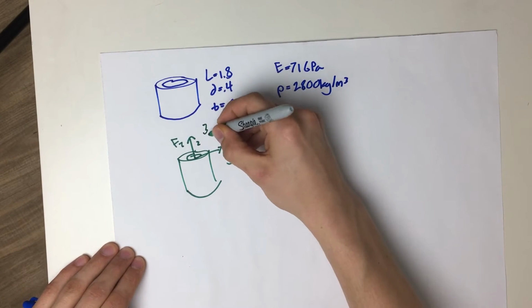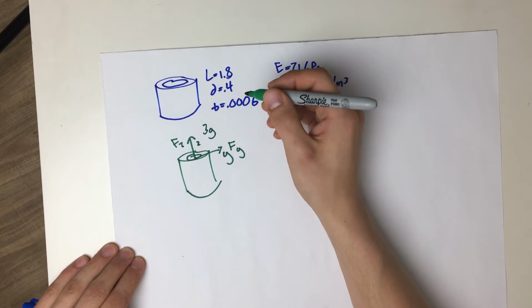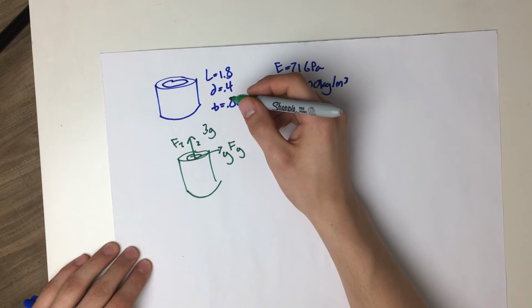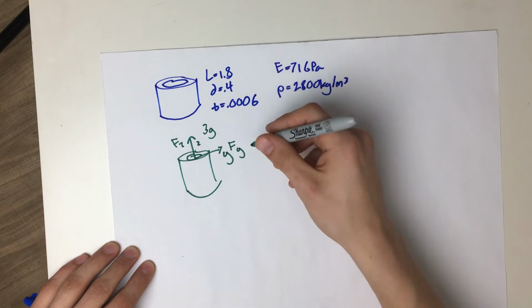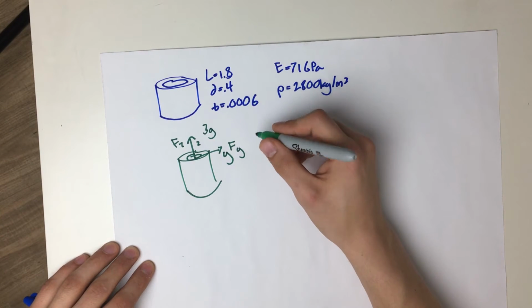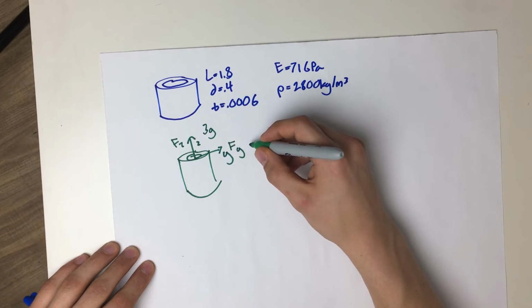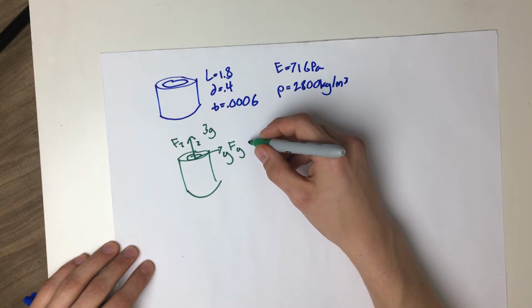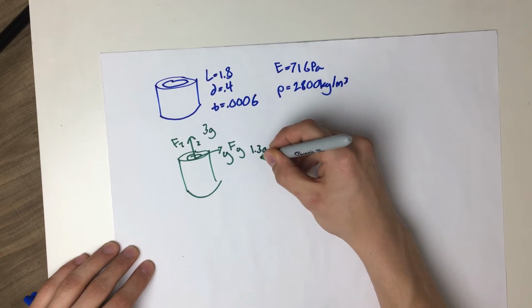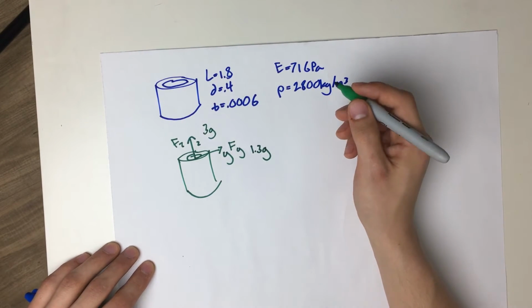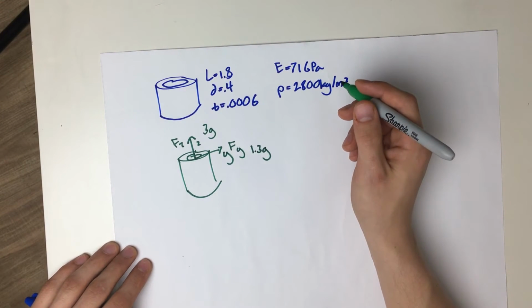So we know from some reference for the launch vehicle that our maximum load in this direction is going to be 3 times the acceleration of gravity, and let's say that the maximum acceleration in any lateral direction will be 1.3, and this is combining the possible static and dynamic loads together.